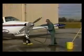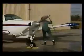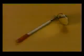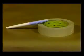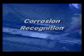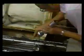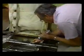You should start all inspections with a thoroughly cleaned aircraft. Some of the inspection tools you will need are a good flashlight, an inspection mirror, a 5 to 10 power magnifying glass, a plastic scraper, and a felt tip marker to mark corroded areas. If you are going to do a good job inspecting your aircraft, you need to be able to recognize materials, proper coating, and damage which could lead to corrosion.